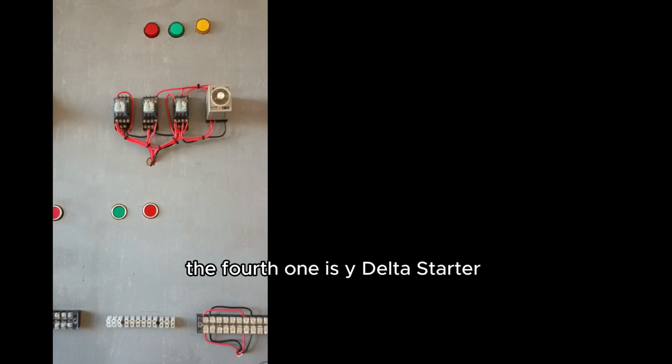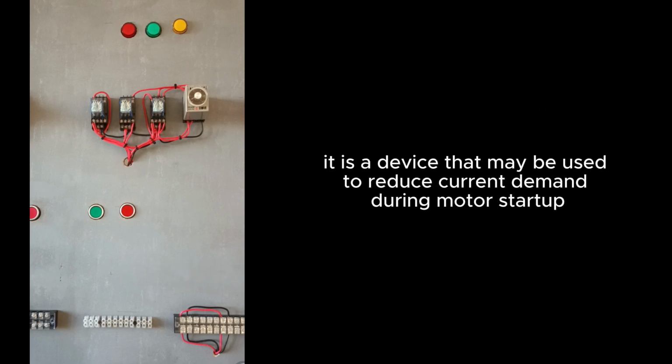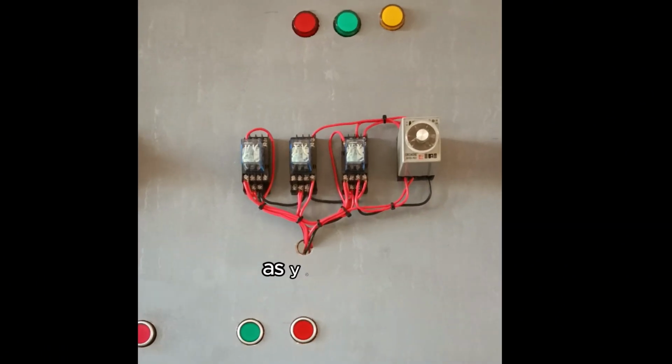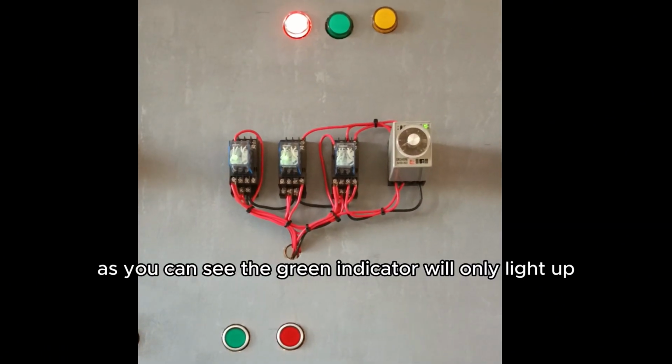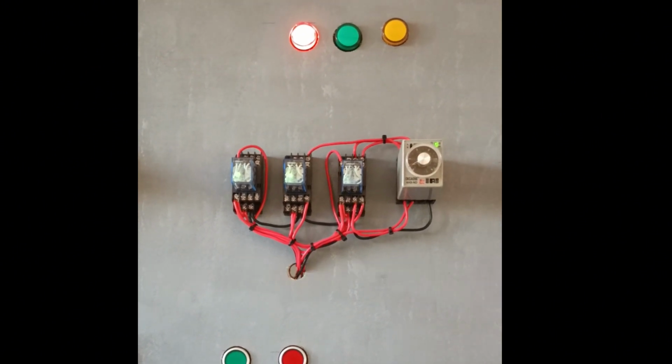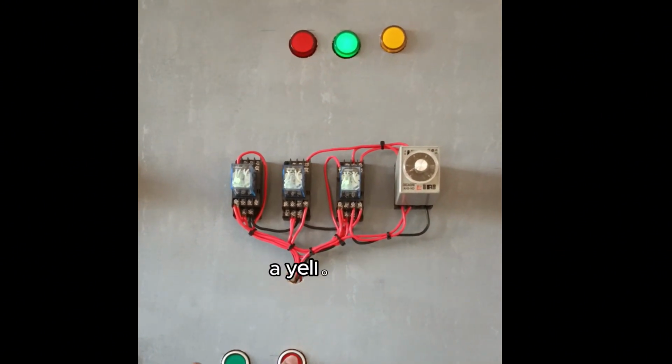The fourth one is Y-delta starter. It is a device that may be used to reduce current demand during motor startup. It is often used for starting three-phase induction motors, but can only be used when starting the motor without load and when the required starting current is relatively low. As you can see, the green indicator will only light up after the predetermined amount of time the red indicator lit up. A yellow indicator is added so the students can continue the wiring themselves.